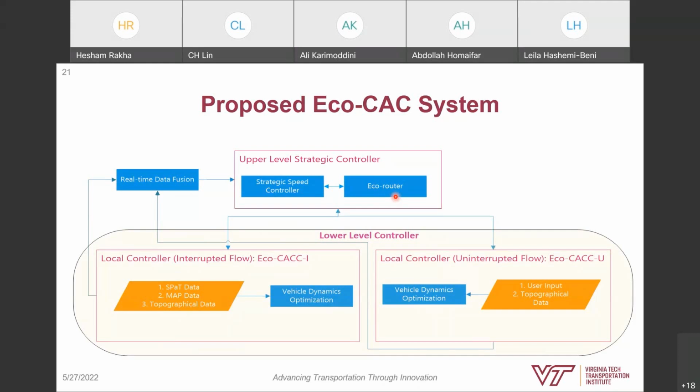So what you could do is try and reduce the amount of traffic entering into downtown Greensboro in order to disperse the congestion in downtown. And in trying to regulate the flow of traffic entering into downtown Greensboro, there are two approaches you could take. One of them is I could use traffic signals and reduce the amount of green time that is being allocated to the traffic entering into this region.